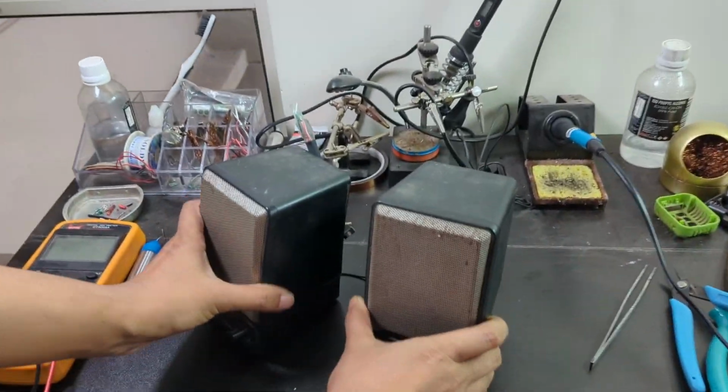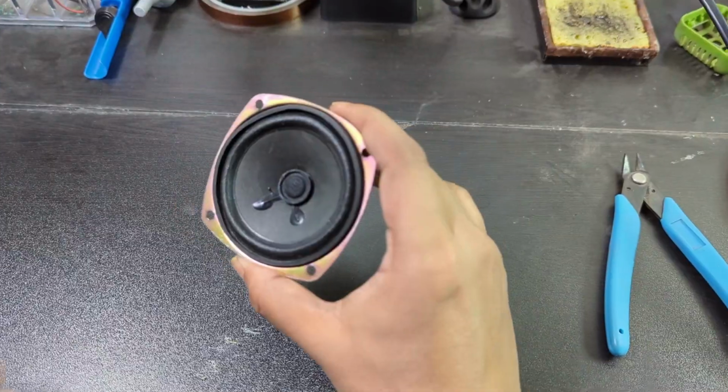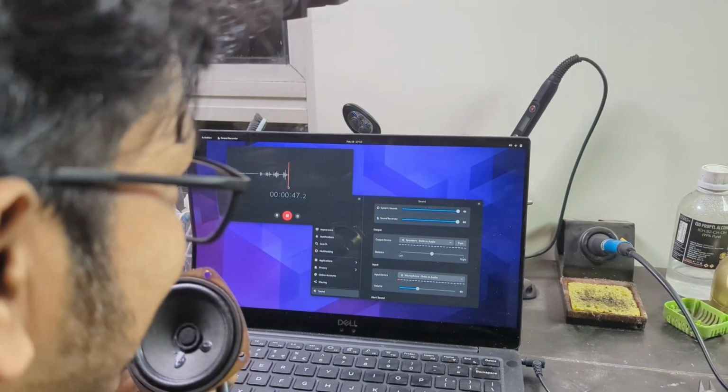Did you know a speaker is also a microphone? The mechanism by which transducers work is reversible. So if you have any broken speaker module, just wire them up as a microphone with a TRRS jack and you've got yourself the most simple form of microphone.